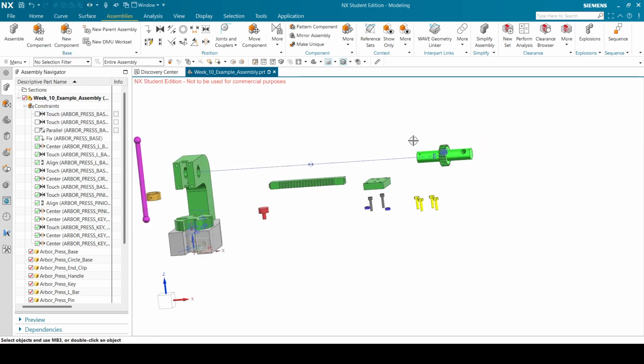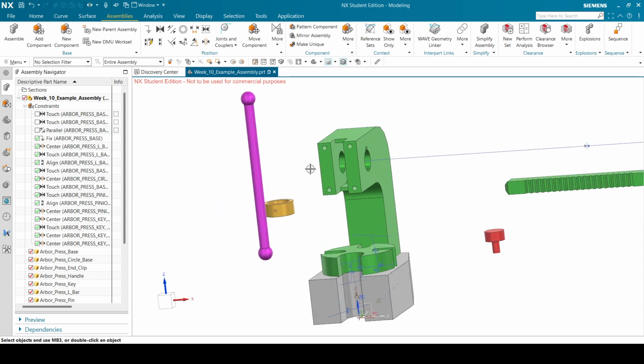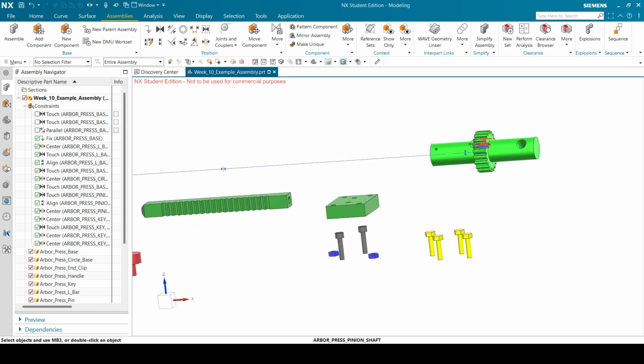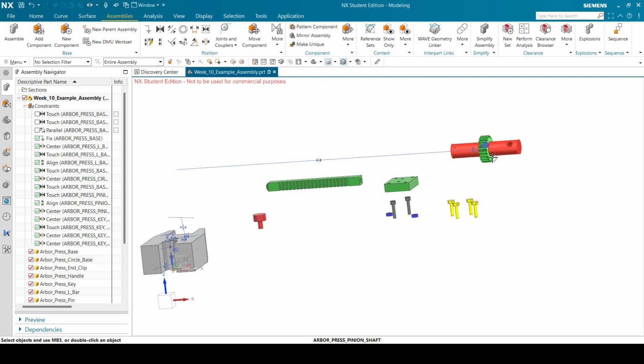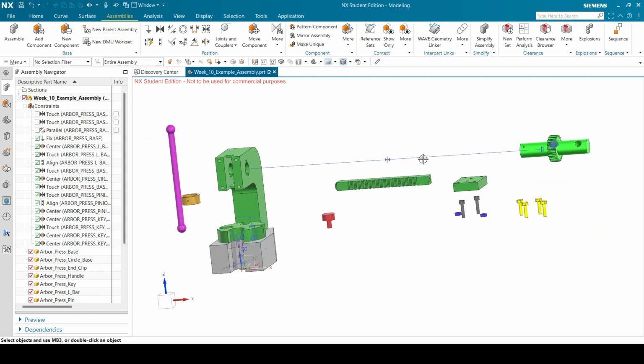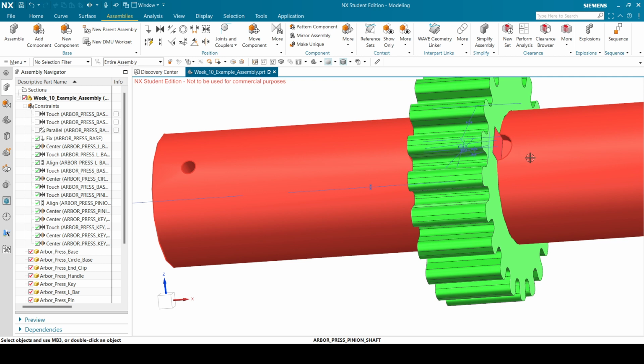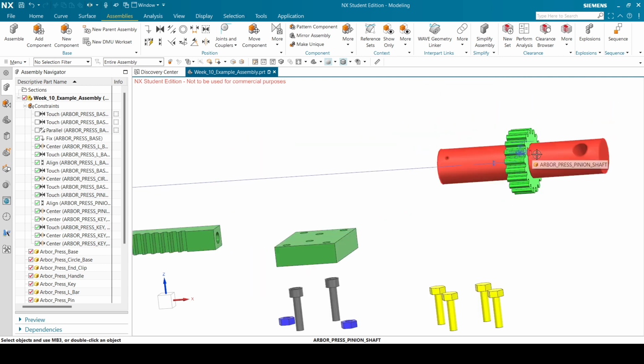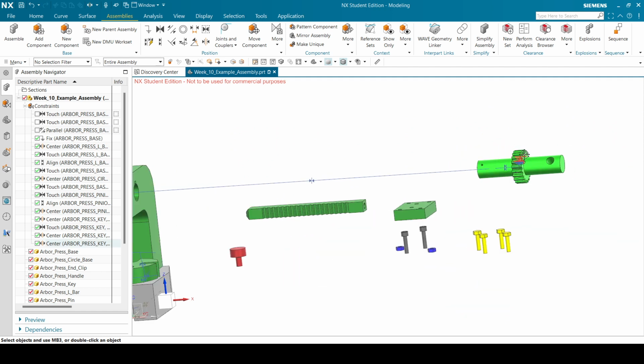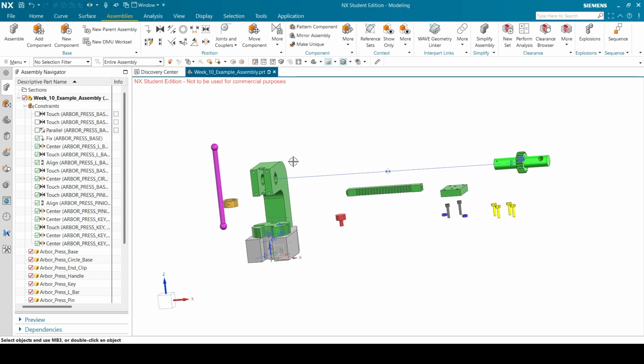Okay. So now that entire thing must go inside of there. So as you can see, in the real world, you first put the gear in there, and then you'll put the key inside of the slot and essentially just hammer it into place. Or rather gently tap, because I don't want to break the thing. But yeah. Okay, so now we can actually go place this inside.